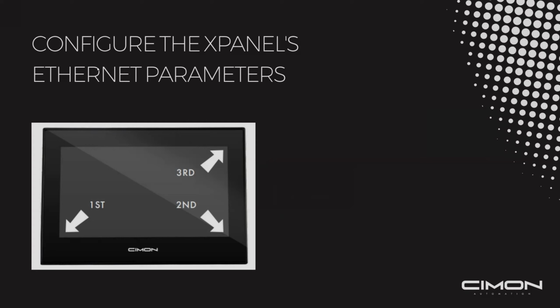You can be shy if you want. But anyway, so how do we configure the X panel's Ethernet parameters? That is, on the physical X panel, we have a method of closing the runtime. That is the bottom left corner, the bottom right corner, and then the top right corner. So by clicking the bottom left corner, the bottom right corner, and then the top right corner, you will open up a window that allows you to close the runtime. And that is how you get to the Ethernet parameters. So let me see if I can show you what I'm talking about by connecting to an X panel over VNC real quick.